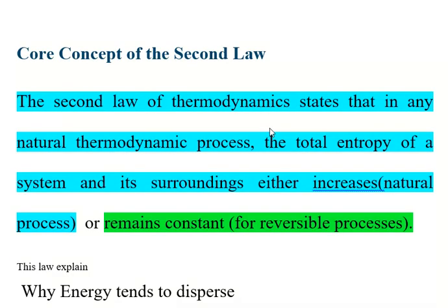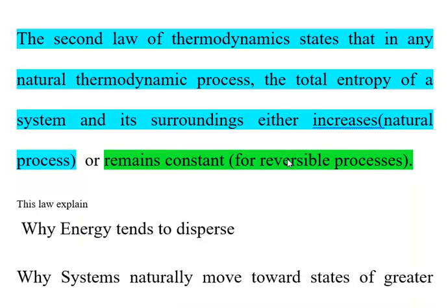What is the core concept of the second law? The core concept of the second law of thermodynamics is that in all natural thermodynamic processes, the total entropy of the system and surroundings either increases, or maybe remains constant. If entropy remains constant, that is possible for a reversible process. Natural processes are irreversible processes, in other words spontaneous processes. So in spontaneous, natural, irreversible processes, entropy increases.